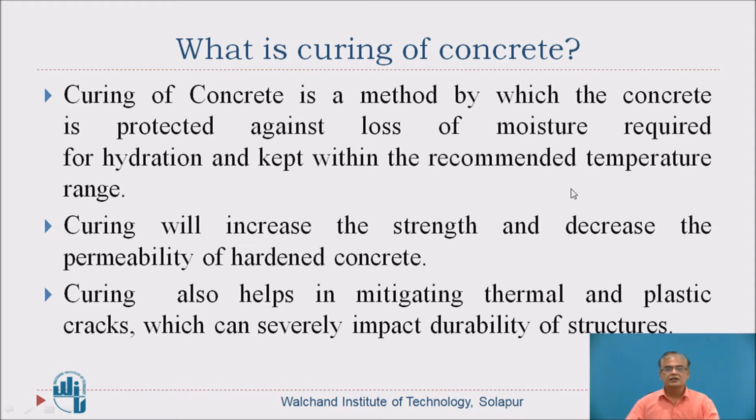So curing is important. Curing will increase the strength and decrease the permeability of hardened concrete. Curing also helps in mitigating thermal and plastic cracks, which can severely impact durability of structures. Remember, friends, curing will control the cracks in concrete, right? Plastic cracks are there, thermal cracks are there. Those cracks can be controlled if proper curing is done.